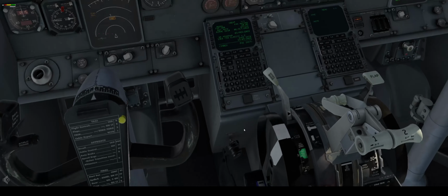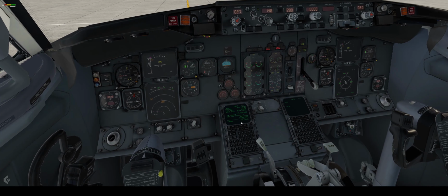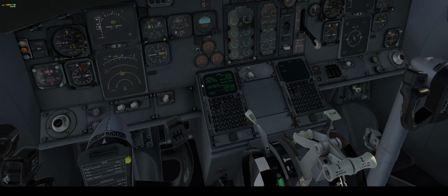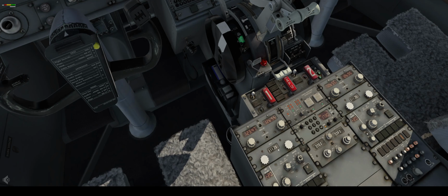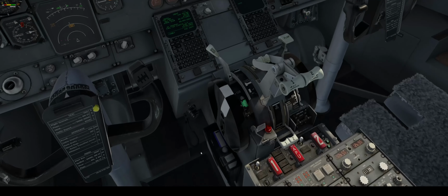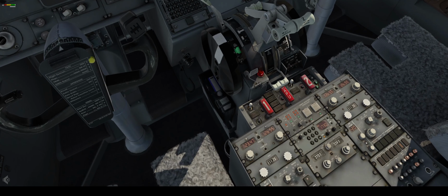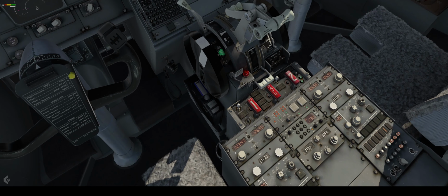So if you have it in auto, that means that your navigation is adjusting your position from VOR, DME sources, and so on. When you press manual, it's the only situation when you press manual, when you are capturing the localizer and then glide slope. Okay, that means manual and now settings. I will find the picture for you.